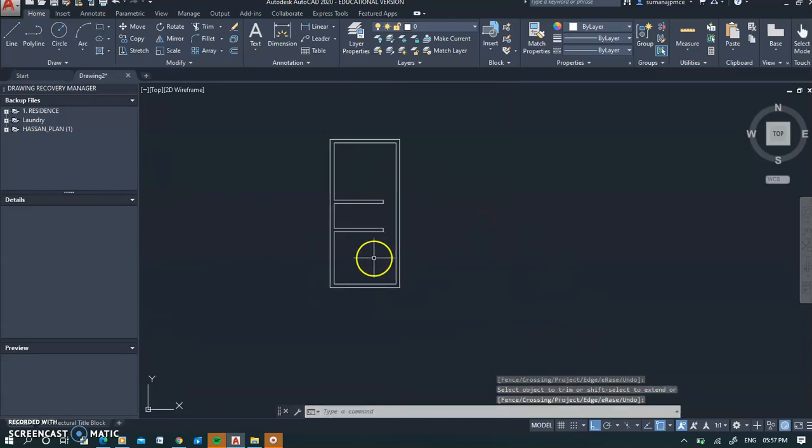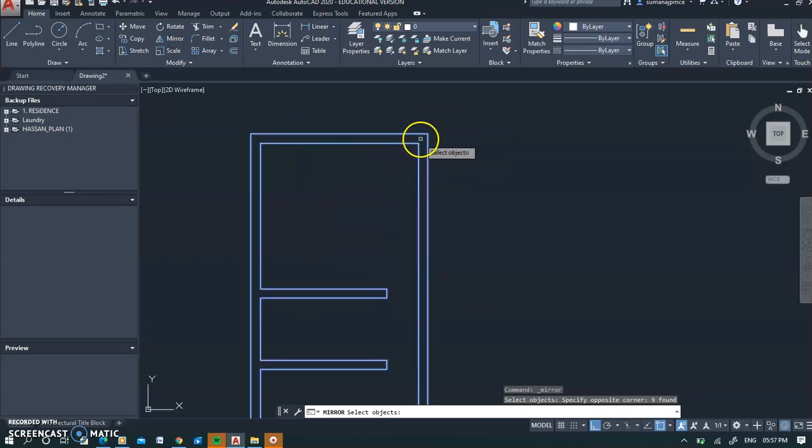So I'm done with 2 rooms and kind of a bathroom. That's what I thought of the plan. Now I want to draw another half of the plan. So what I will do is I can copy, or I can mirror this whole image. I'll do that. Mirror. Okay, I'll mirror this whole image onto the other side. But I want to have a mirror line which should be exactly in between this wall.